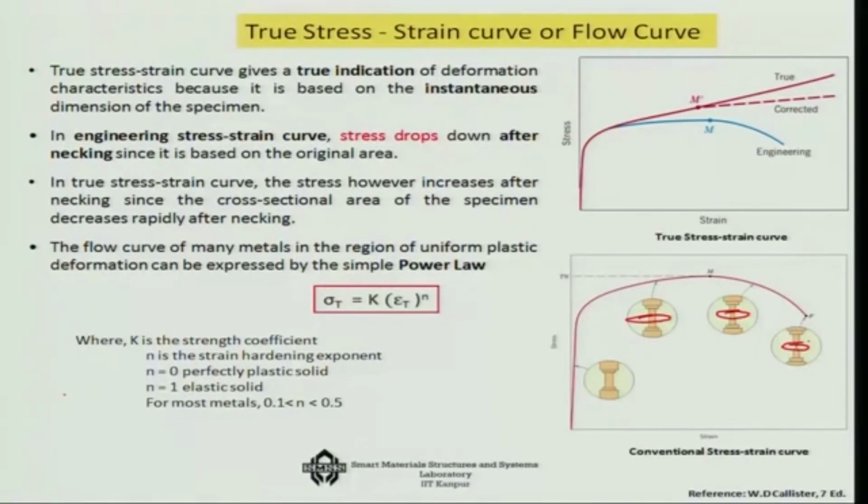So, the area is changing, and if you consider that actual area, you will see that the stress strain curve is not drooping, but it is actually increasing, and it is increasing because even if the force you are increasing, the area is actually decreasing at a very rapid rate. So, that is why the true stress is increasing at a very rapid rate.